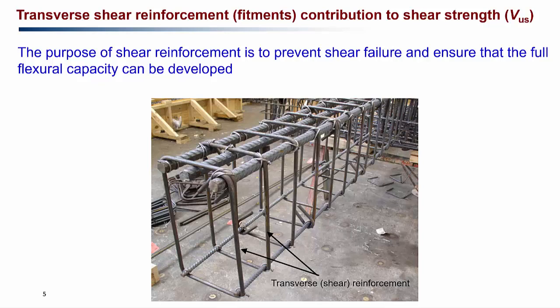Otherwise, when the diagonal cracks appear, the concrete will crack, and the crack will extend from the tension side to the compression side abruptly, and the beam will fail. If you have shear reinforcement, these cracks cannot appear and the shear capacity is increased. So let's find out what the contribution from this shear reinforcement is to the shear capacity of the beam.